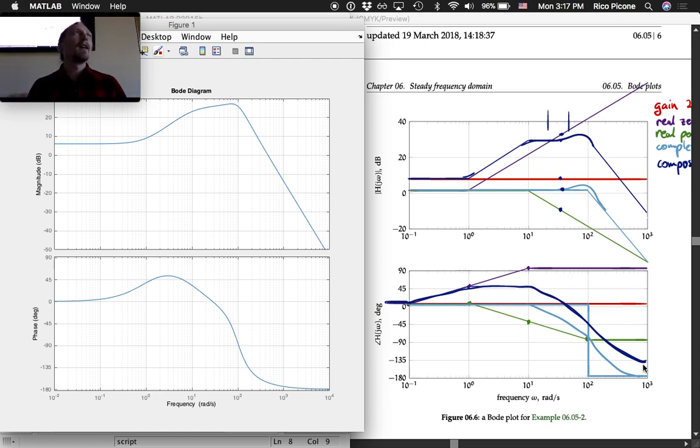And we're trying to think about, okay, this parameter's contribution, this part of the transfer function, how is it contributing? Yeah, approximately we have a pretty good sketch. So it's really easy in MATLAB to come up with a Bode plot. The Bode function actually gives you access to more than just plotting it, though. You can actually get the magnitude and phase information from that if you wanted to. Make your own custom plots and whatnot.